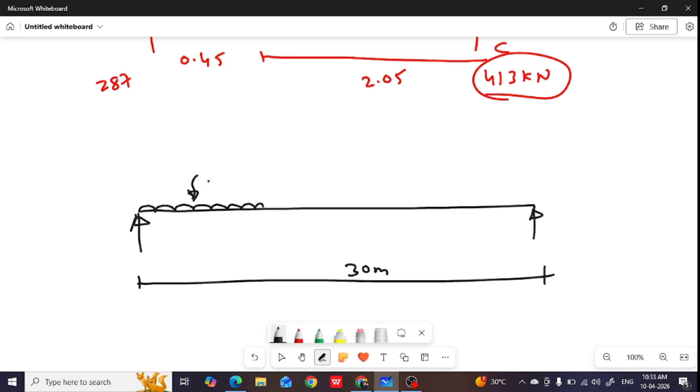And how to find this intensity? Already we have gotten the reaction on girder C. Reaction divided by contact length. Okay. So this is coming as 114.72. And maximum reaction you will be getting at the left support. That is 388.21 kilonewton. Okay.